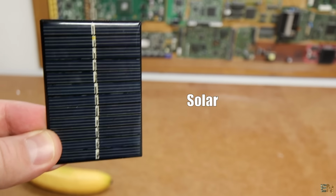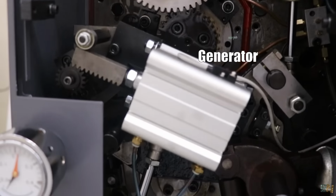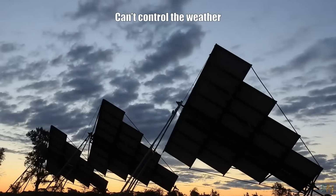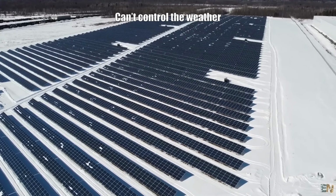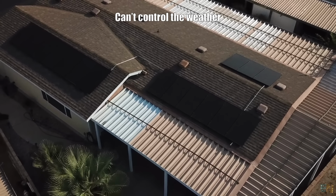But a variable power source would be something like a solar panel, or maybe a wind turbine, or a generator powered by a motor, for example a gasoline motor. In the case of the solar panel, the output will be variable because you don't know if you will have a lot of sun or if it will be cloudy or raining that day, so the voltage will drop. Or maybe outside is very cold and the output of the solar panel will be affected by the cold temperature or by the hot temperature, and you don't know if there will be some shadow, so maybe half of the solar panel is covered but the other half is not. So depending on those variables that you don't control, both the voltage and the current from this panel will be different at any time.